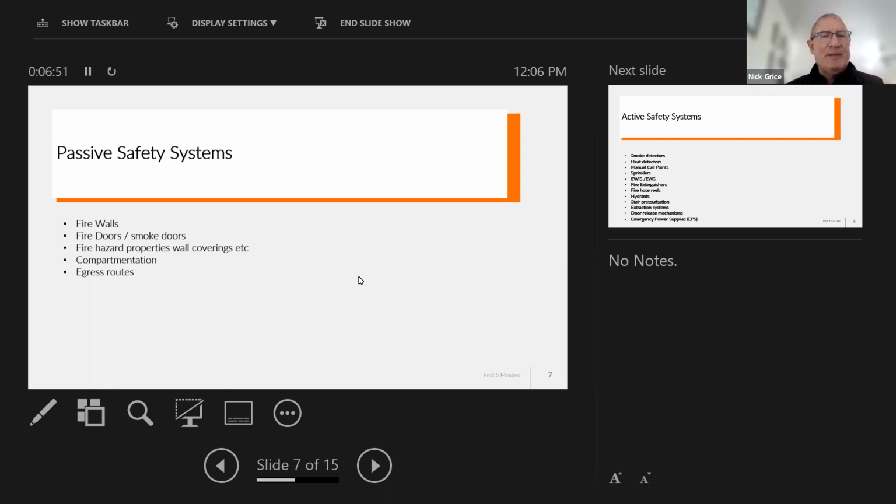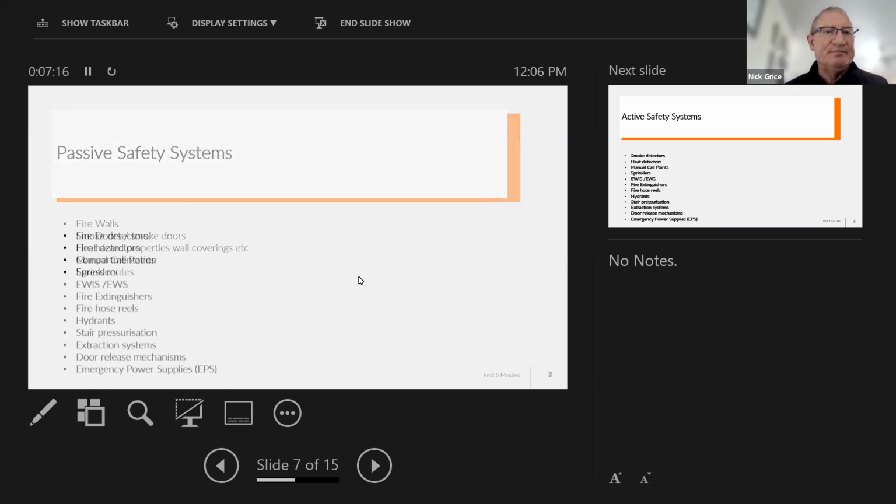And that's why in hospitals and things, in 4083, we do basically a 3-stage evacuation process. So it's not once the alarm goes off, you get out like in a normal office. You can go stage evacuation. So stage 1 is behind one set of doors, stage 2 is behind another set of doors, stage 3 is outside. Now by then, the fire service should be with you.